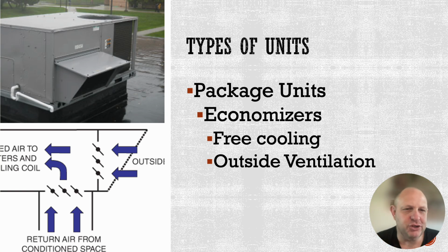Referring to the package units, something that's very nice about outdoor equipment is our ability to use what we call free cooling. So if the humidity level is correct outside and if the temperature is correct, we can take that air that is on the outside and push that air into that environment, cooling that environment down.